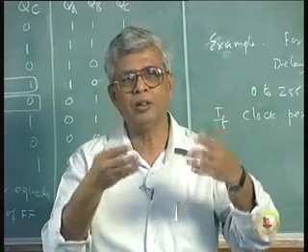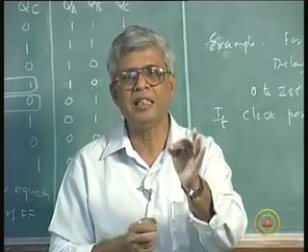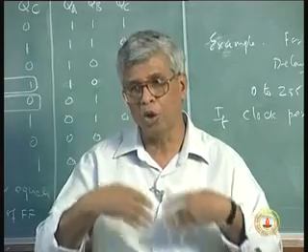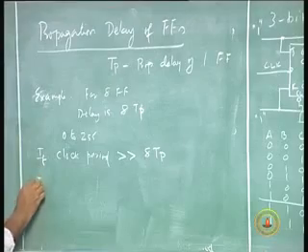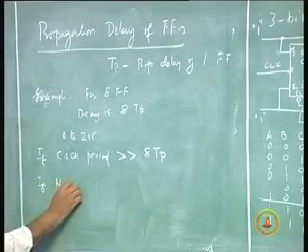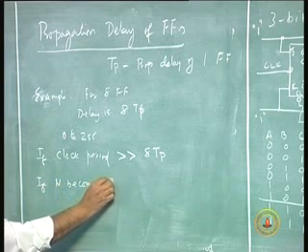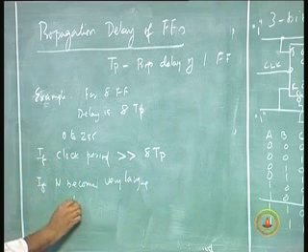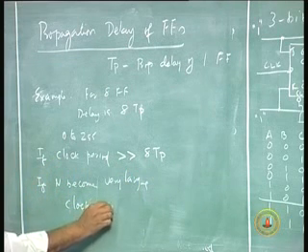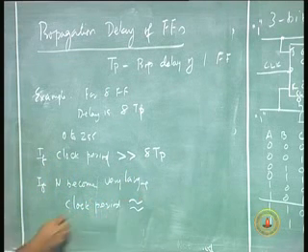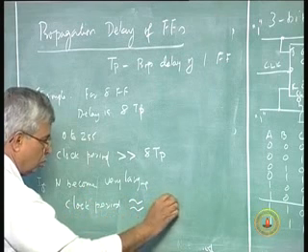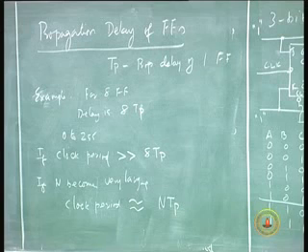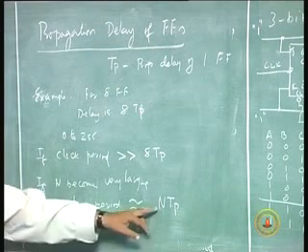What if it takes 8 Tp to settle down? 8 Tp is an insignificant part of my whole clock period. But supposing I have a larger number of stages, if n becomes large, the clock period may approximate the value of the propagation delays of the n flip-flops.